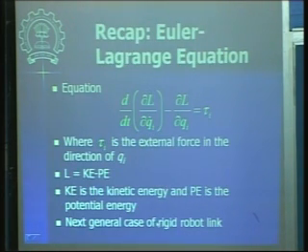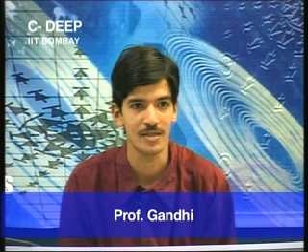Okay. Now let us again come to our basic equation, the Lagrange formulation. Okay. Now what we want to do is to extend this understanding so that we are able to apply it to our robot manipulator. Okay. So for that, just imagine what you need for applying this technique to the robot manipulator. So first thing is how to find out the kinetic energy of your robot. Okay. So what is the general formula for the kinetic energy?